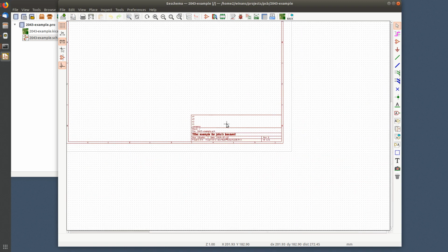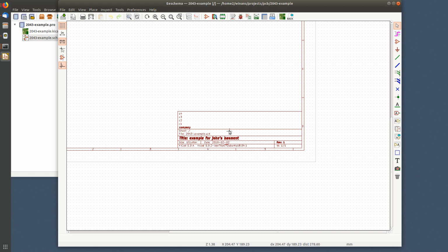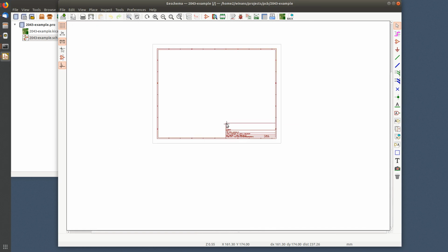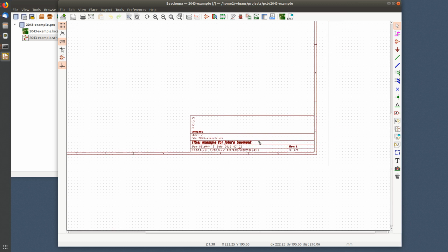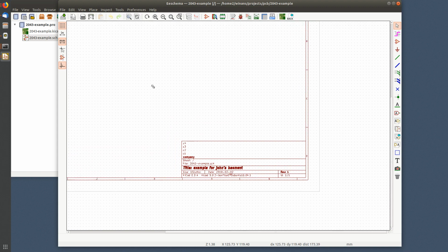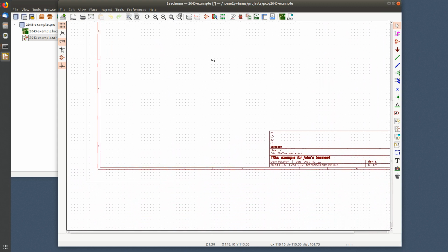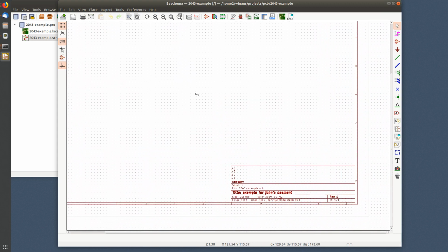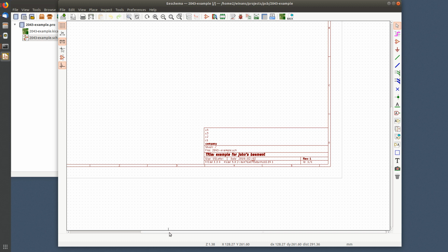Now I'm using my mouse wheel. I move the cursor over an area that I want to see in detail. Like, let's say I want to zoom in right on this box corner. I move the wheel forward. I move the wheel backwards. So just so you understand what I'm doing when I'm zooming around. When I'm panning, what I'm doing is I go to some place I want to grab, and I press the middle mouse button, which in my case is the wheel. I push the wheel down, and I can grab the sheet and I can push it around. If you don't like doing this, you can obviously grab these scroll bars down here as well, and the one on the side like this.